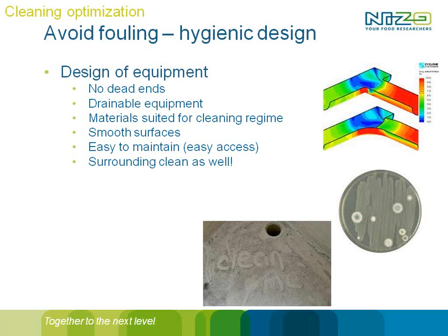Moreover, your equipment should be drainable, so try to avoid a layer of water or remaining product or cleaning fluid or whatever inside your equipment. After cleaning it should be clean and dry, or at least no water or product or cleaning fluid left inside the equipment. The materials should be suited for your cleaning regime.